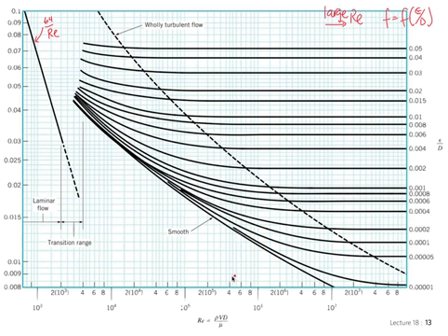Now for flows with moderate values of Reynolds number, around here we have dependence on both the Reynolds number and the roughness, all of this area. I can clear a spot here and say this is both a function of Reynolds number and roughness.